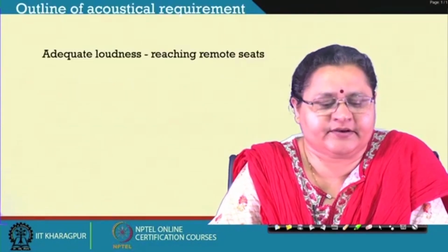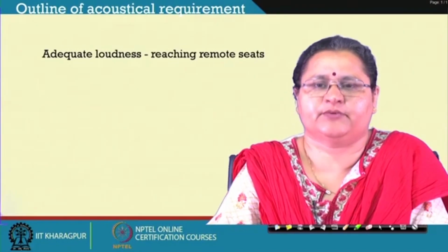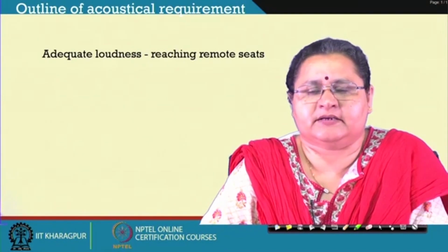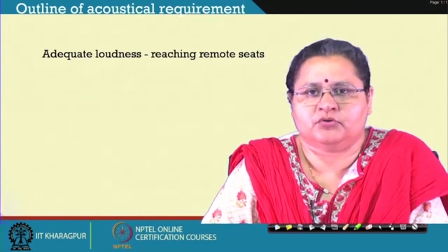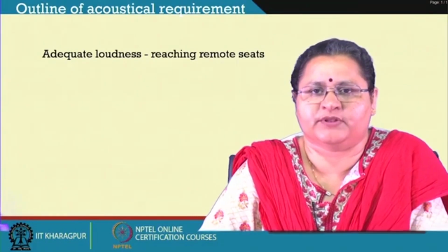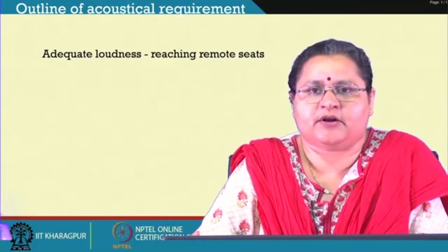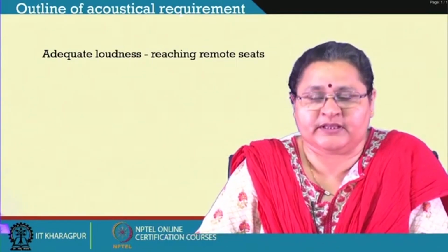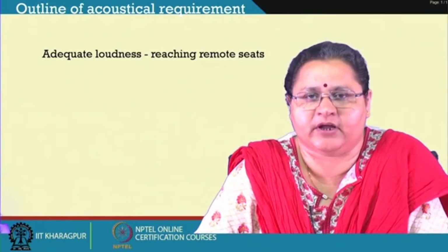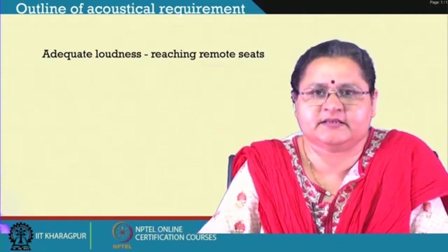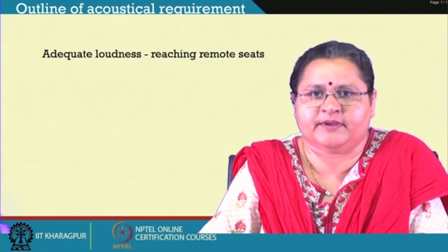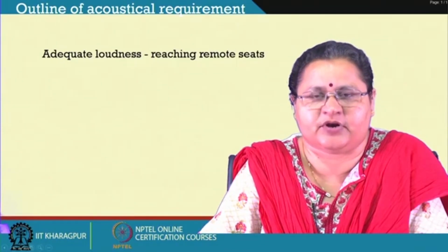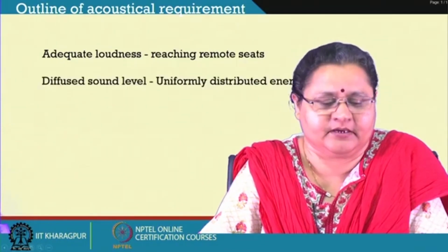Now, coming to the acoustical requirements, we first need adequate loudness. It is no more a small space, and a source sound without any reinforcement or electroacoustics cannot reach the end of the hall if the sound source is not loud enough. So, reaching the remote seats is the first requirement, so that the auditorium is a success at any seat or any point within the sitting area.